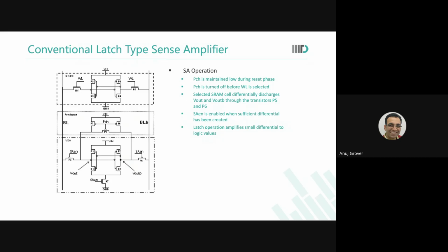Two devices were intended to be matched, but at the time of fabrication, one device had a little higher VT. So let us say this device had a little higher VT. So you require the input to be slightly lower to get the same effect as for this device.